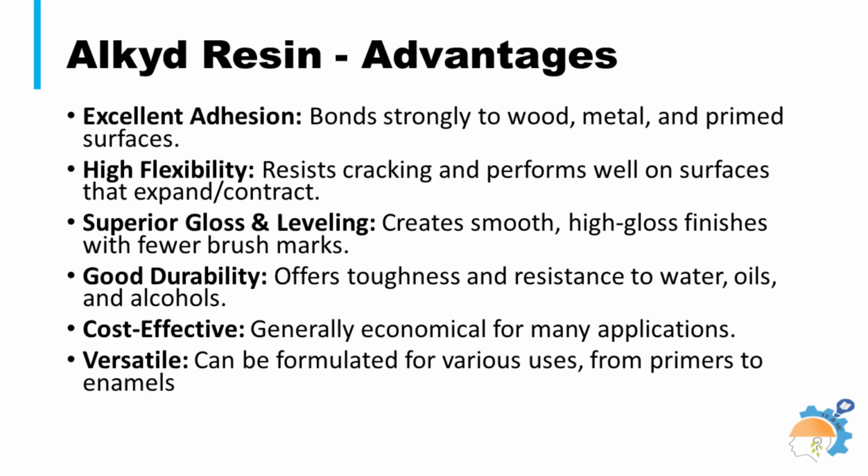Alkyd resins offer great adhesion, flexibility, gloss, and durability, making them suitable for wood and metal, but they suffer from slow drying, strong odors due to VOCs, potential yellowing, and difficult cleanup, requiring thinners. Although these provide excellent value and performance, especially for industrial primers and decorative paints, modern demands push for faster drying, eco-friendlier alternatives.